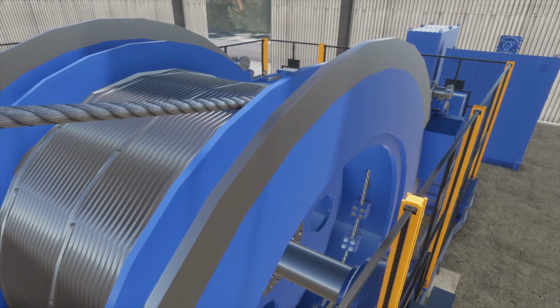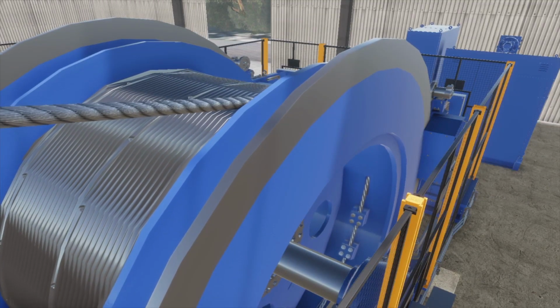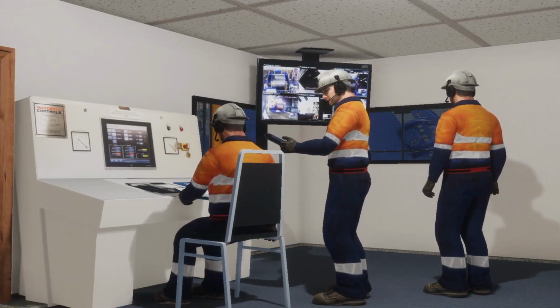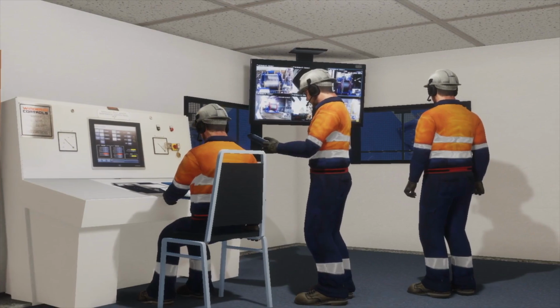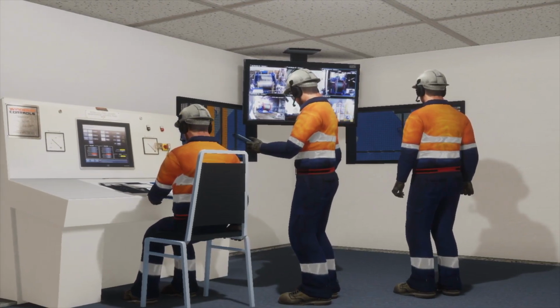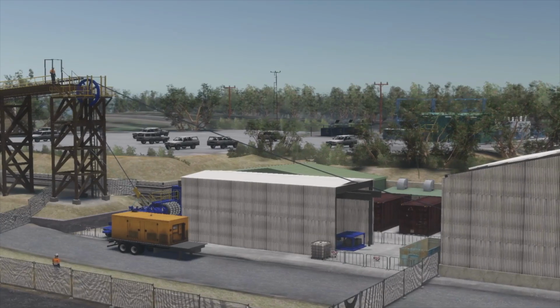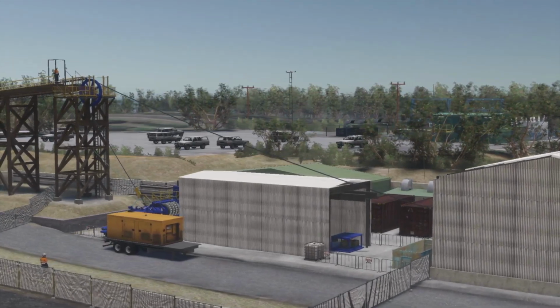The friction winch and winder were then used to slowly apply a load to the rope, while the rope tensions were compared between the load cells, friction winch and winder readouts to ensure that all items of equipment were reading as expected. When the rope end reached the head sheave, the friction winch, hydraulic reeler and winder were isolated.